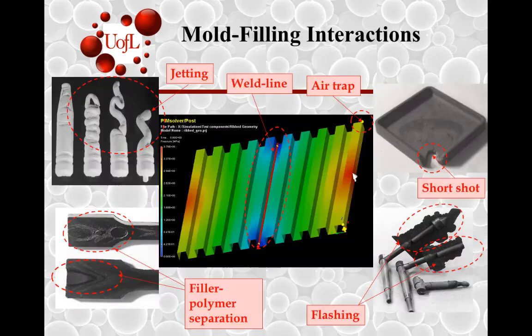Where are these considerations important? Let's take a typical injection molding scenario where a plate like this with all these channels is getting molded. If you don't get the viscosity right, either by choosing an incorrect injection pressure, melt temperature, or mold temperature, or not being sure of the geometry, you can have premature freezing of the mold. That's called a short.